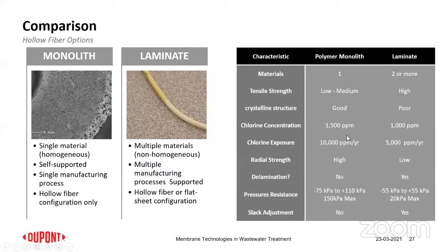In the case of wastewater, when there is organic load, the easiest thing an operator would do is to purge the system with chlorine. And if the membranes fail from chlorine attack, then the very purpose of using membrane filtration would fail, and you will not get the defined filtrate quality. So the most important quality that a membrane should have is very good chlorine tolerance in the case of an MBR.